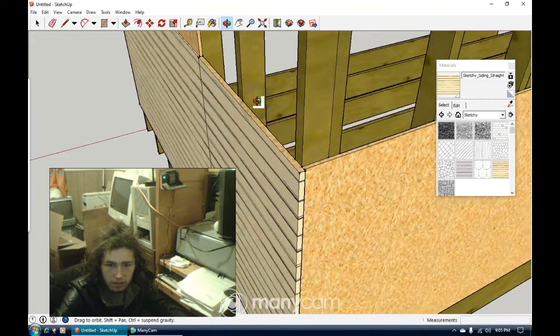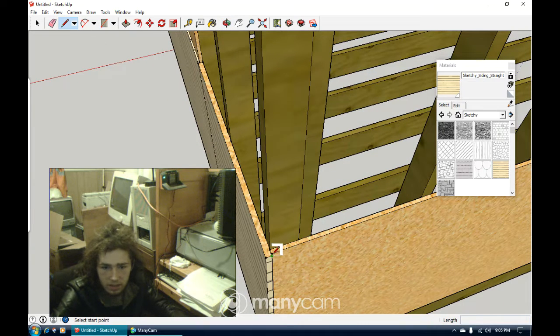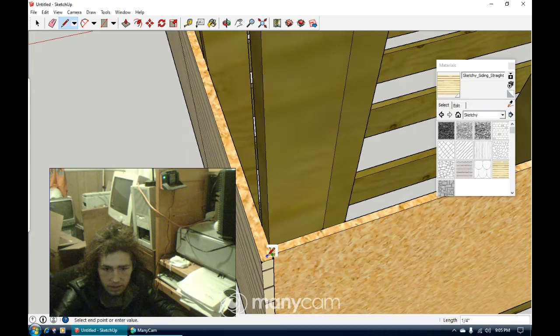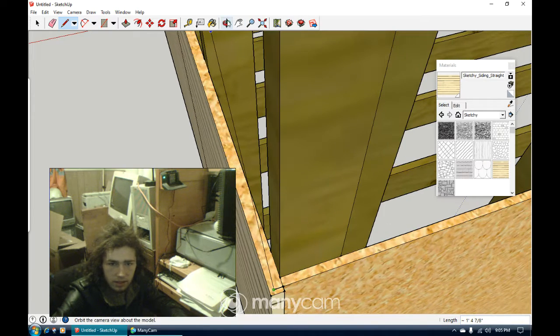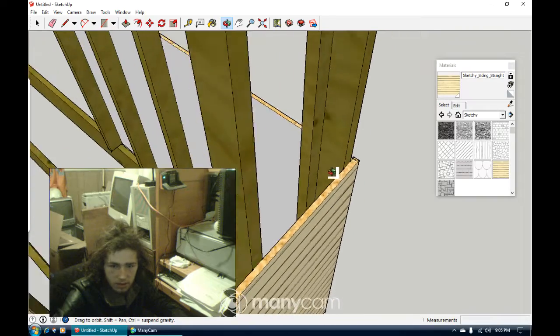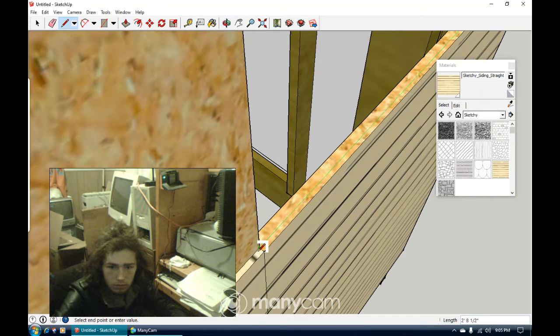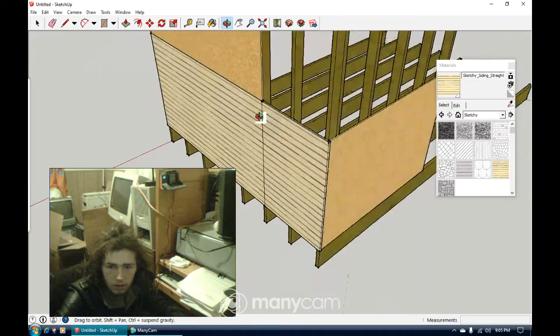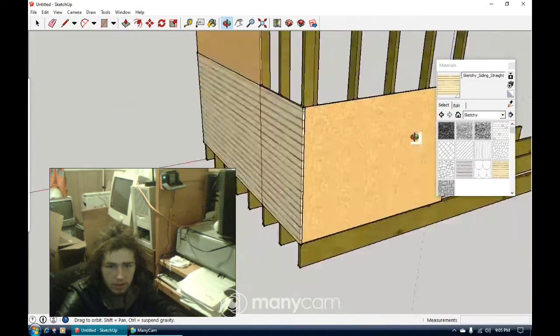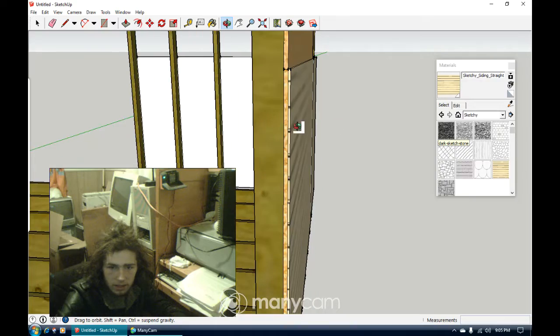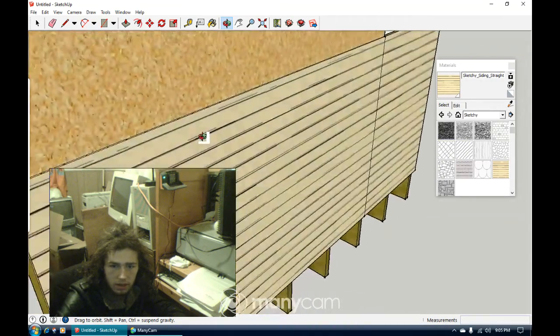and here's where matching can get tricky. You want to mind the thickness of the plywood, because what we're going to do is create a line here that is a 1/2 inch. And then we're going to take that line as a base, and we're going to put it right over here. And now we have siding and then a realistic cutaway of each individual layer.